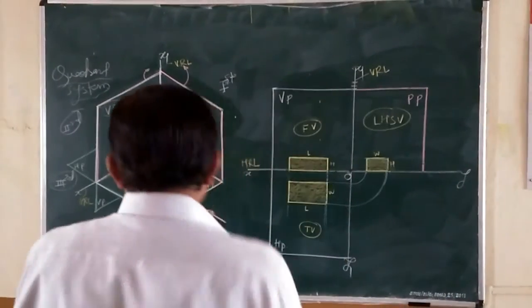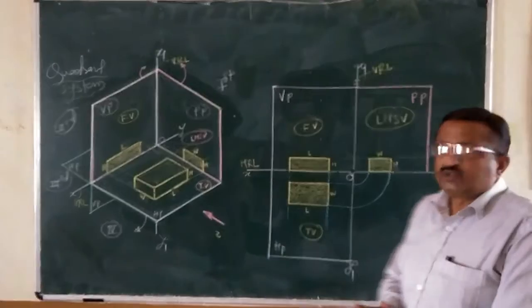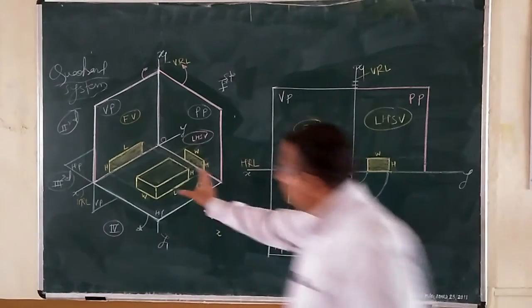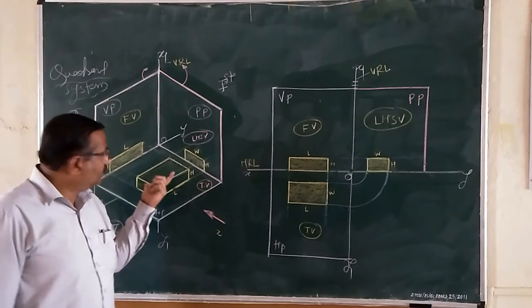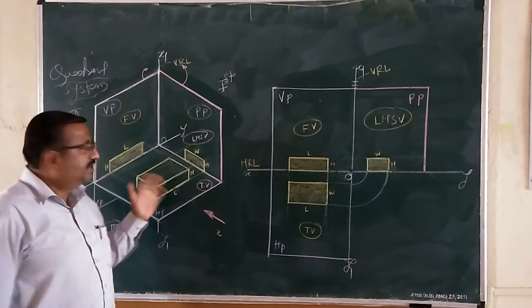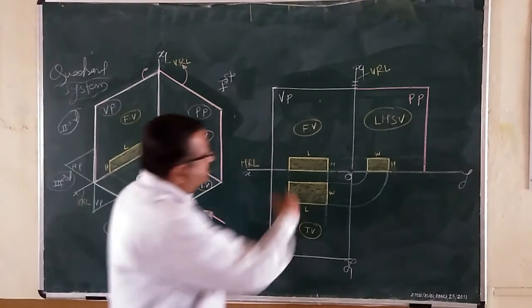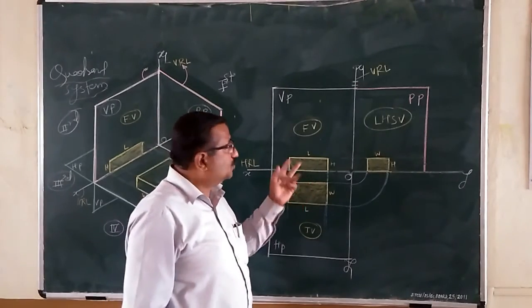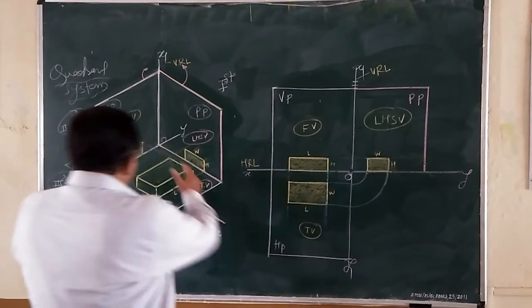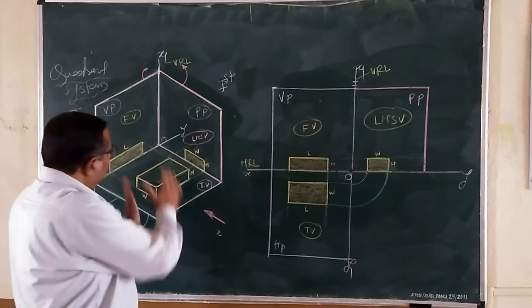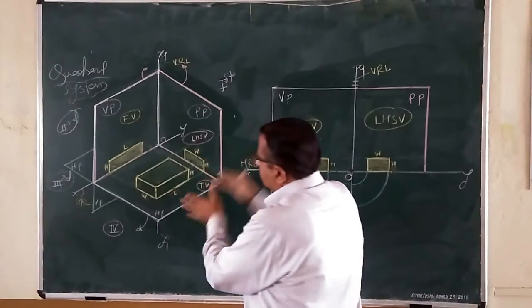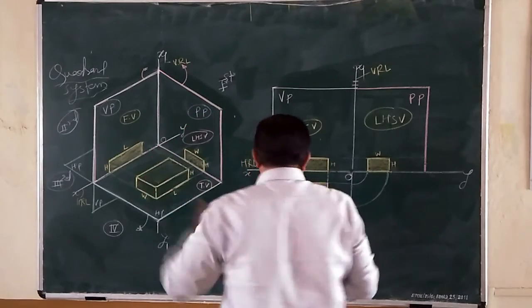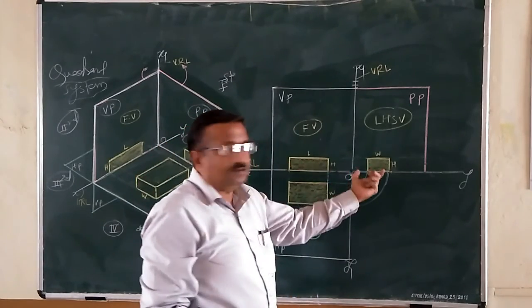So this is nothing but the exact solution of this object, means the conversion of this pictorial view, this isometric view, or what is called the three-dimensional view, into orthographics. Orthographic means two-dimensional, three number of views. Earlier it was a three-dimensional pictorial view. We have converted it into its front view image, its top view image, and its side image. Front view, top view, and side view.